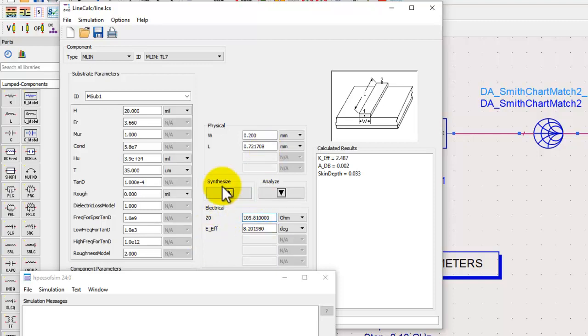The second anchor point is how wide a line can they etch. So usually, roughly on a typical fab house, they can confidently do something like 3 mm, but usually they don't have any upper limitation, but mostly they recommend you to use only up to 3 mm. Now, if we give 3 mm, we get another bound, which is more for capacitive line, and here we can notice lowest I can go is around 24 ohm, which can be confidently printed on my PCB.